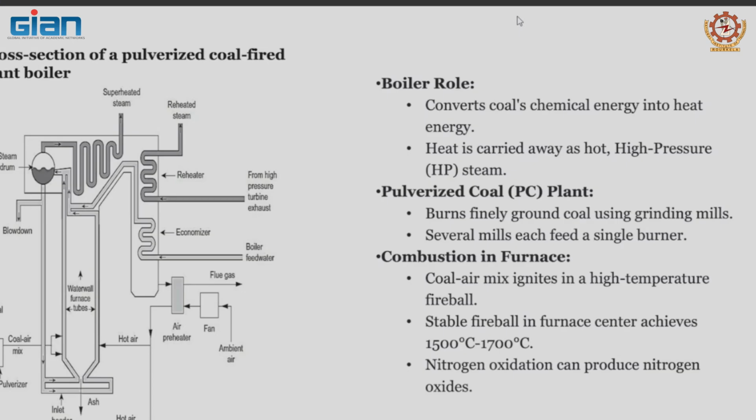The idea of the fuel injector is to atomize a liquid fuel into a mist to give you the largest surface area to mass, or volume, ratio, with surface exposed to oxygen, to give you the highest combustion rate. In this case, pulverizers mimic atomizers. Coal goes through a number of physical processes, sorting, and then it goes through pulverizers.